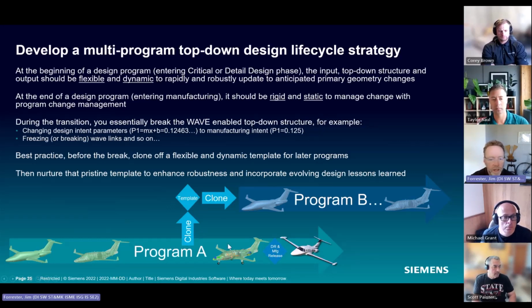At some point in time, you're going to start changing those driver-driven relationships, those design rules, those equations, from equations to hard, fast rules. An example being here, where the radius of a fillet in the pocket of some hog out is being driven by an equation, and it goes off forever.